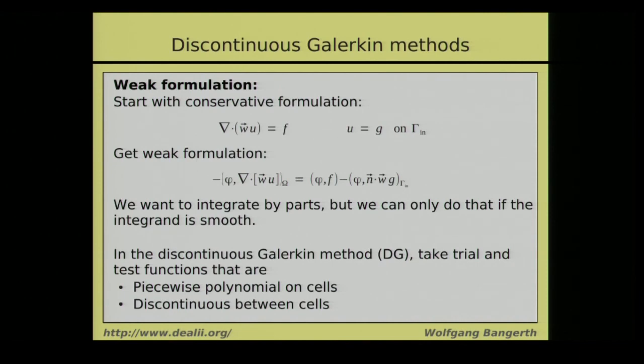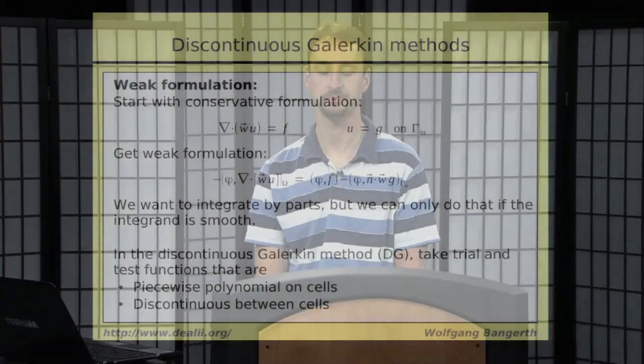So what I want to talk to you about in the rest of this lecture is an alternative approach to finite volumes that we call discontinuous Galerkin methods. Discontinuous Galerkin methods date back to the 70s, but I think the real power has only been understood in the 1990s, when people realized that we can introduce a particular way of dealing with finite elements where the shape functions that we use are not continuous anymore. But let's say we allow functions that are discontinuous from one cell to the next.